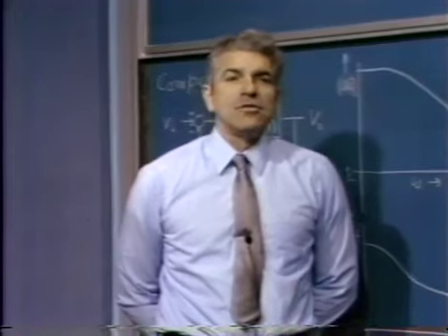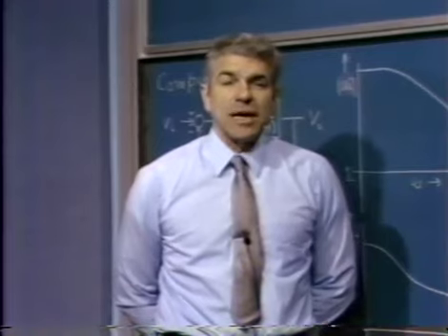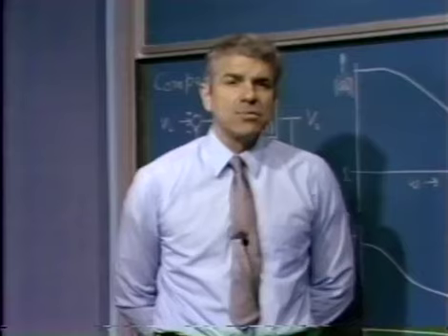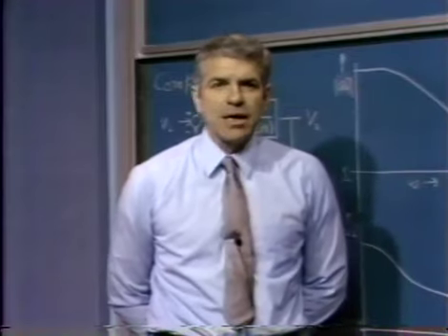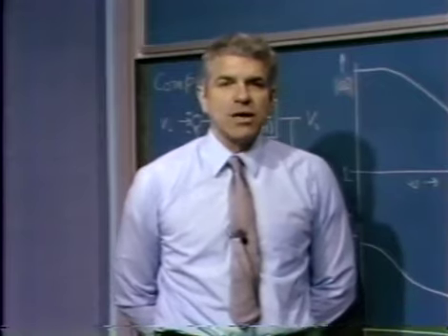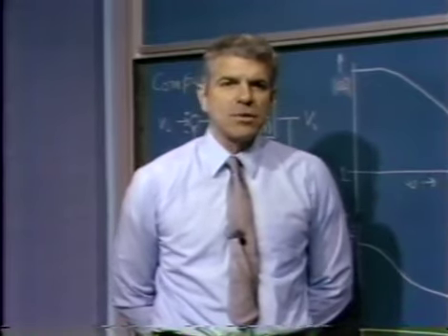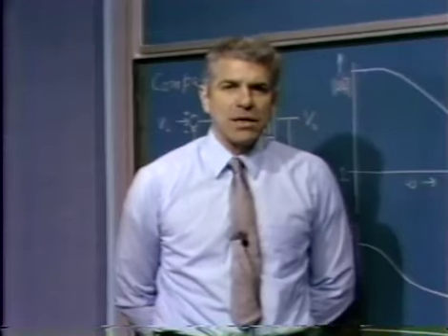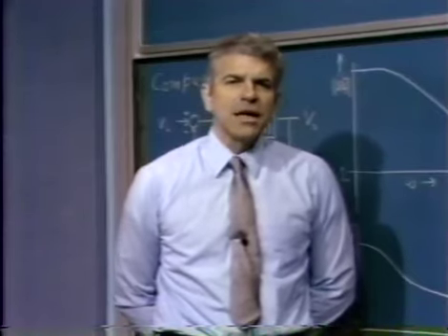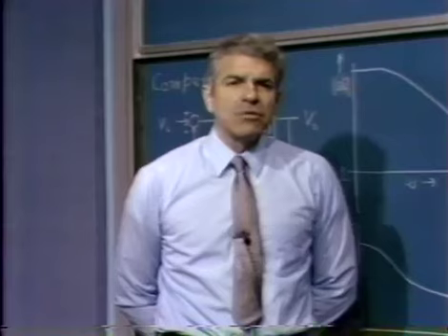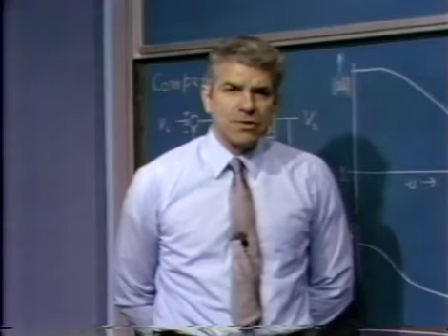It does give you a measure of how much margin you have, how tolerant or intolerant you are to changes in various system parameters, how sensitive you are to changes in certain quantities that affect the loop transmission magnitude. For example, if we had a gain margin of 3, then increasing the loop transmission magnitude by a factor of 3 would cause the system to become unstable. But if we have a gain margin of 3 and are sure we'll maintain it, it has relatively little influence on the stability, the relative stability of the system. The big indicator of relative stability is the phase margin.